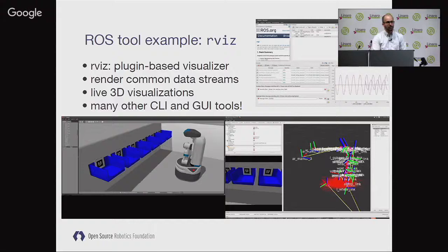There are many tools available in ROS. The most popular one that we see people use is the ROS visualizer, or RViz. That includes a bunch of different components in it. It's highly configurable, and you can assemble all the different visualization widgets in panels and save those configurations. So no matter what the robot platform is or the application you're working on, you can generate a configuration of RViz and then save it so that you can speed up things in the future.